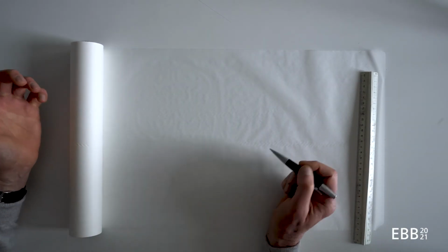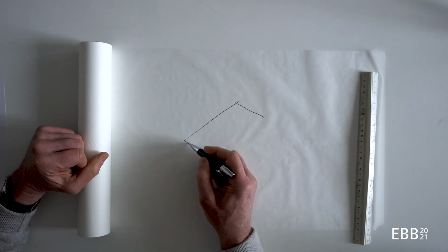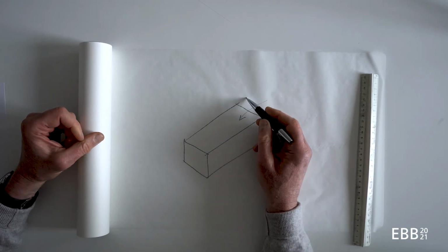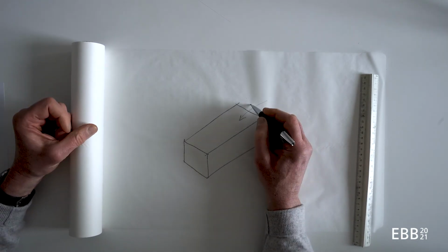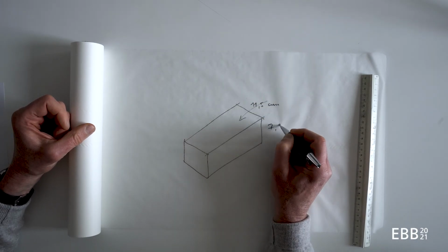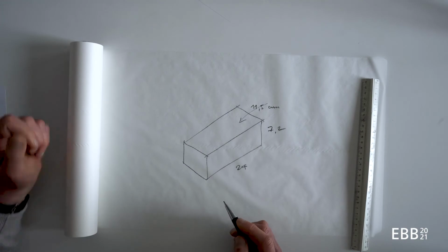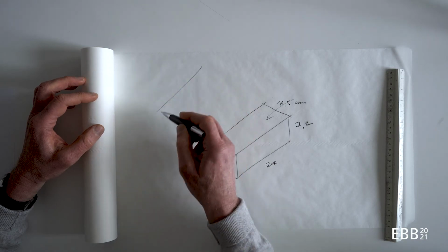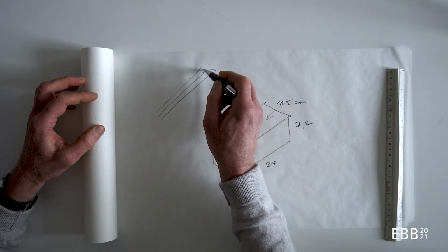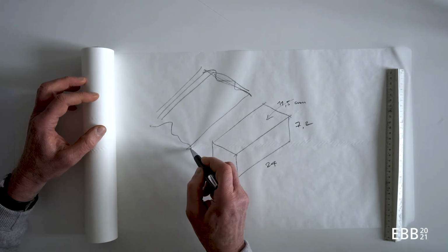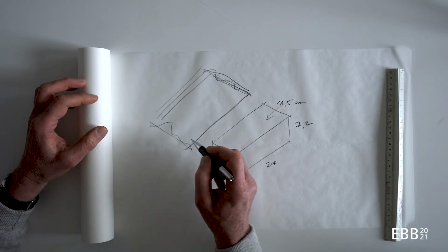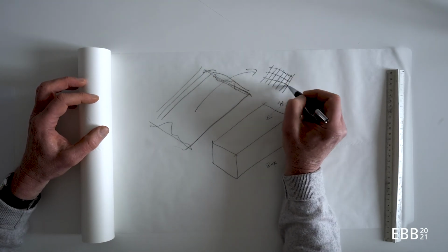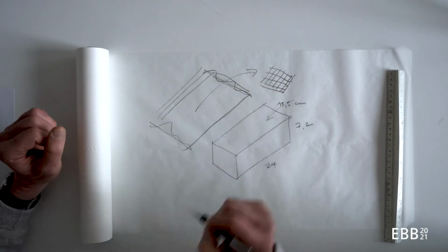And a last important quality of materials are delivery sizes. For example, German bricks are 11.5 centimeters wide, 7.2 high and 24 long. And it's important to know in which dimension elements are delivered. This is also valid for roof tiles, for example. And these roof tiles might have a certain dimension, and you have to respect this dimension if you cover a roof with these roof tiles, so that you have no leftovers on the side.